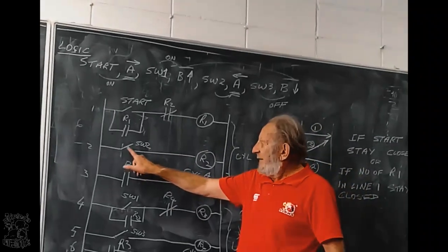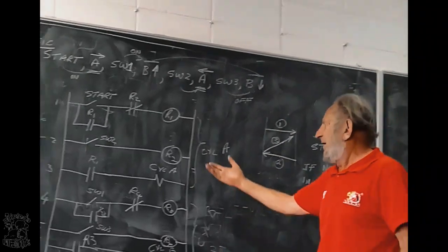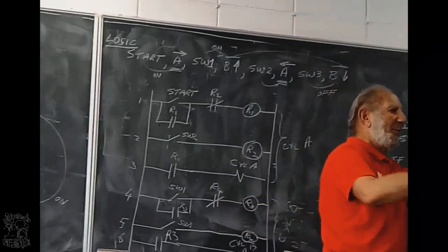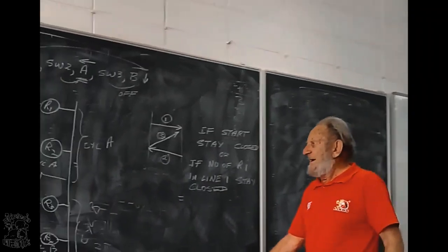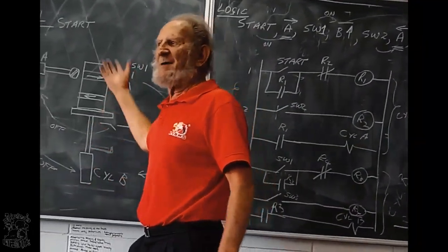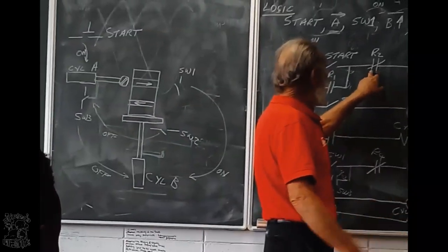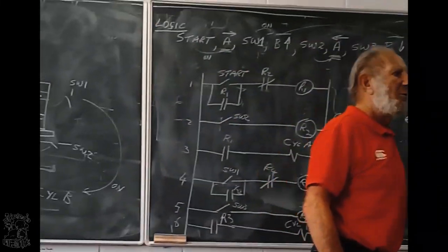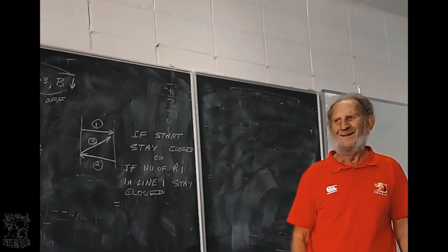What will happen if switch 2 stays open? Same as what we had before. That implies that you don't get power to open that. So it will cut the first groove, B will move up, the machine will stop. What will happen if it touches switch 2, and then when cylinder B goes back, switch 2 stays closed? If switch 2 stays closed, that means relay 2 will be open all the time, will complete the job, next job cannot start.